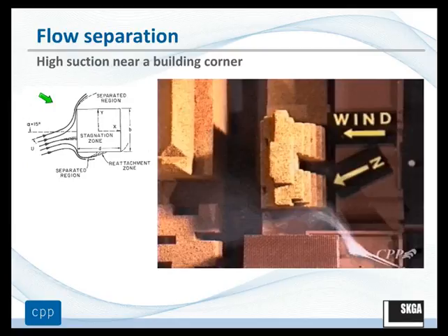which shows as the wind approaches from the left and hits this square block, you're going to have positive pressure all along the front wall. But at the corners, it separates. And this one especially, the separated area has some curvature to the flow and an area in here we call the separation bubble. And there can be very high negative pressure there.